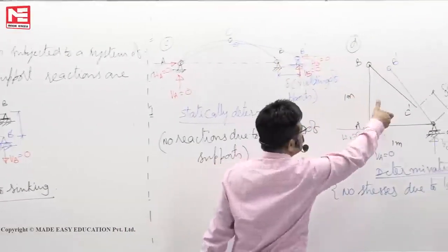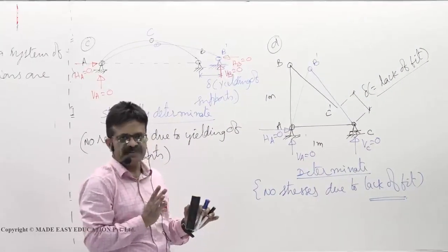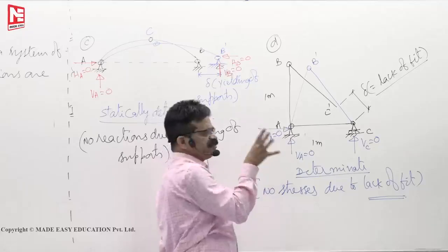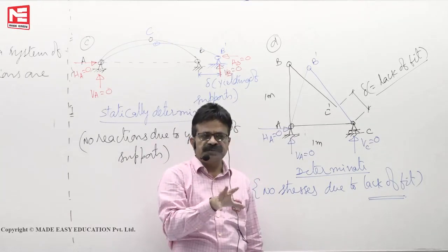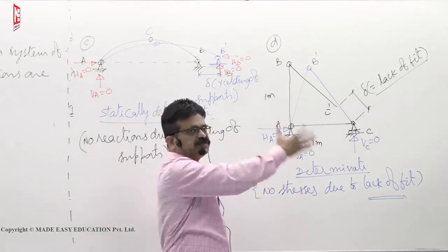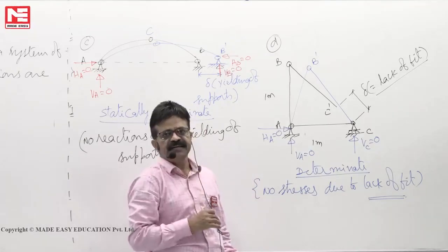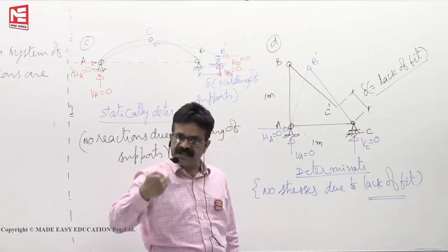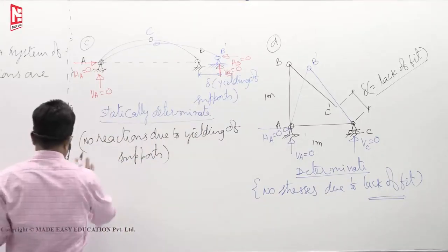As a rigid body, they will rotate without developing any stress. Why does it rotate as a rigid body? Just a sufficient number of reactions only are there. So it will not undergo deformation. Either it will translate or rotate in a statically determinate structure due to these external actions. So we can write a conclusion like this.